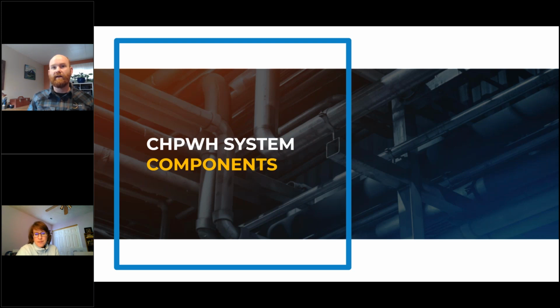Some of the Nyle units use R134A as a refrigerant, so it's going to struggle at lower ambient air temperatures compared to that CO2 refrigerant. And then Sanden, or SanCO2, through Small Planet Supply is also offering skids. Once again, that's more of a residentially sized heat pump water heater, but can definitely be used in a commercial application, and we've had a lot of great success with that. Great. And Richard, I'll put in the links to those manufacturers for you so you can have that going forward.